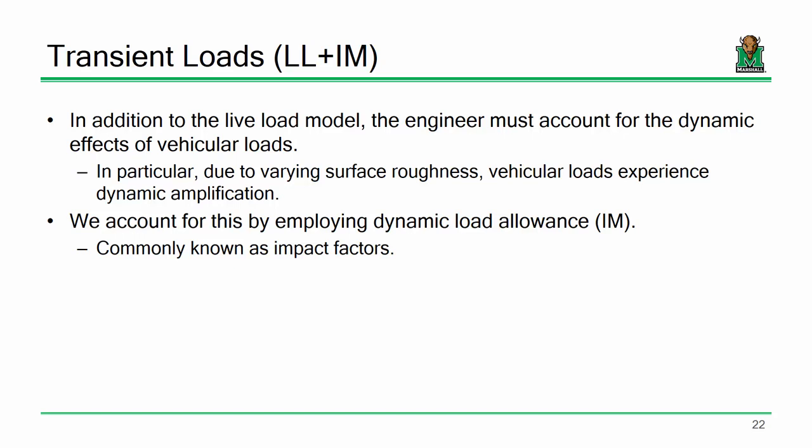All right? When we do live load analysis, we have to be realistic about things. And one of the parameters that we have to assess is the idea of dynamic effects. What I mean by that is when we do a structural analysis problem, there's a beam with 20 kips sitting at the middle, and we just assume it's been there forever and that load is static. That's not how bridges experience loads. Bridges see trucks go on there very heavily.